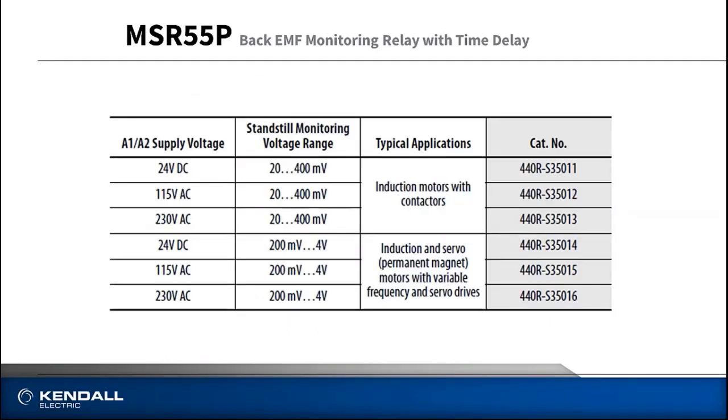When ordering, make note of what type of motor you have. You will see in our chart that a VFD and servo application will require a larger standstill monitoring voltage.